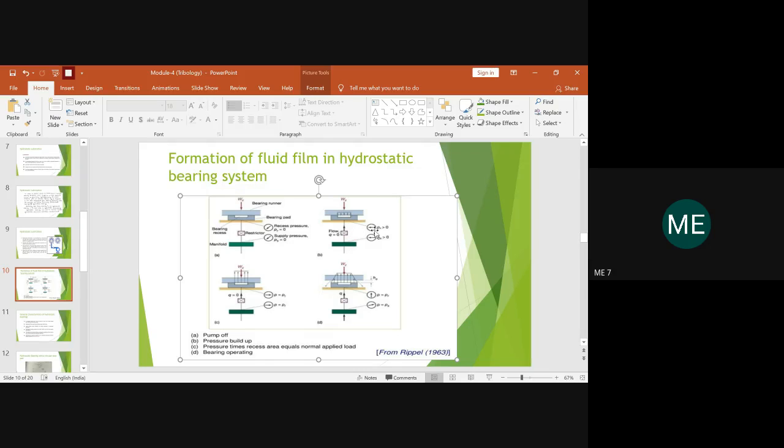Even due to this pressure, across the recess, which is the bearing recess, the white one, the pressure will go high, it will be greater than 0, right? And this pressure which is developed here should be equal to the load distribution which is coming from the top end.